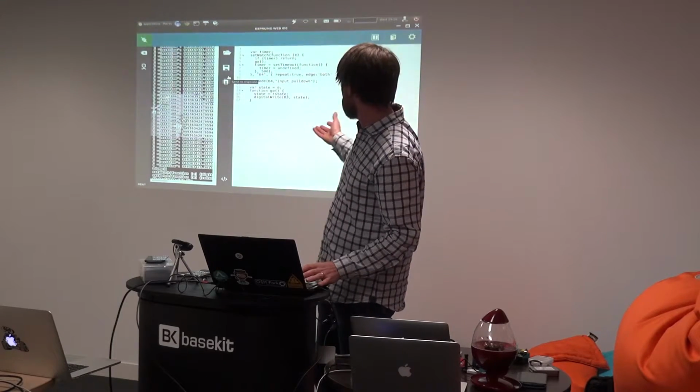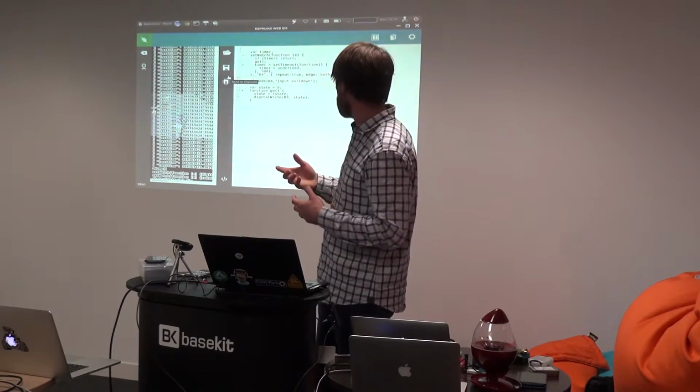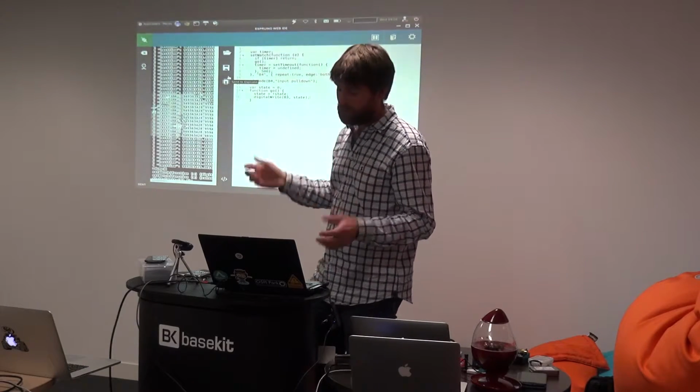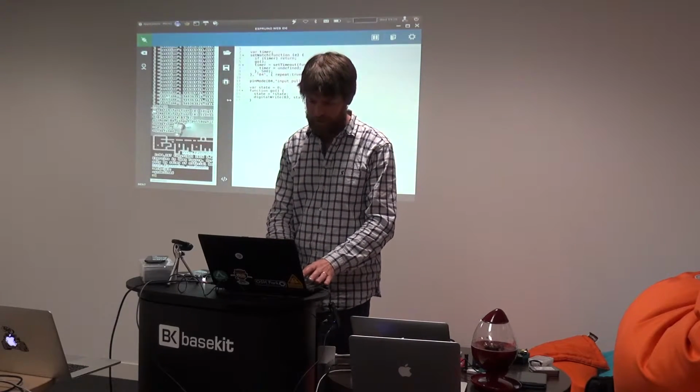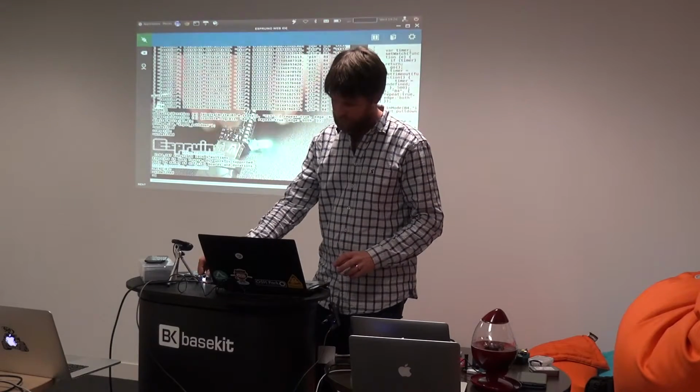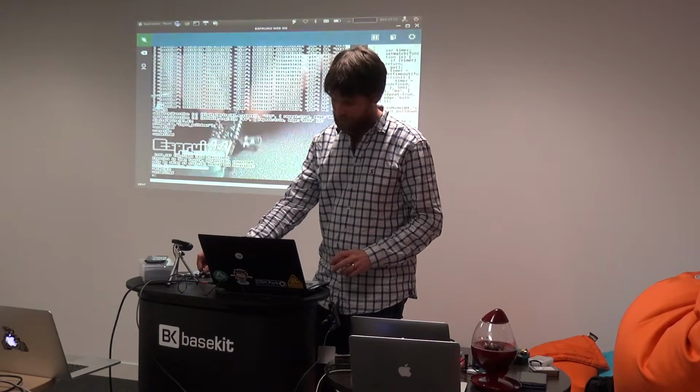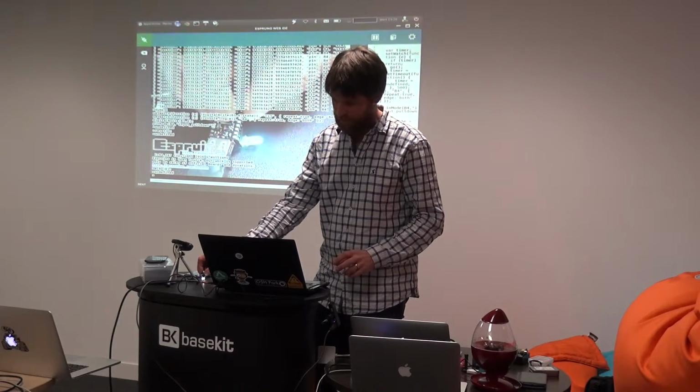so now every time that function is called, it will just change the value of state, and it will write to B3, which was our light. So upload this, the light's lit up, and if I shake it, hopefully, pretty much every vibration it'll change.